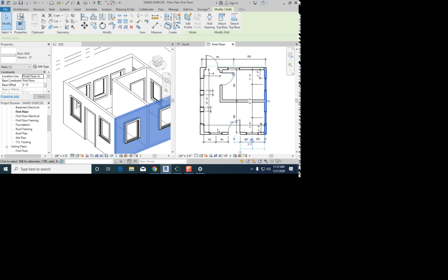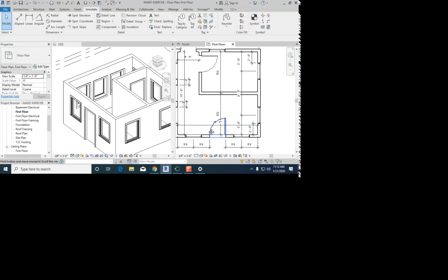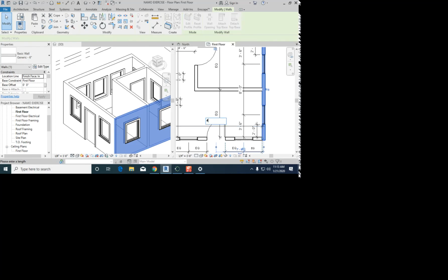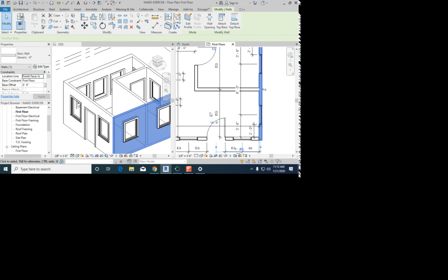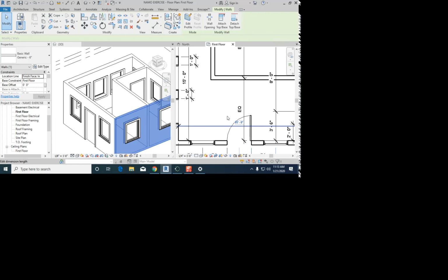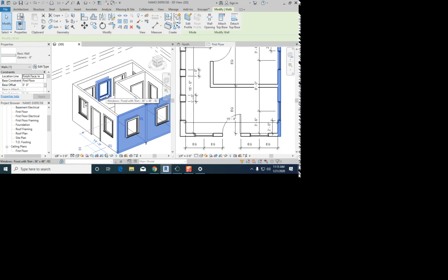And then Olivia, the other thing that you might have to do when you're done. So let's see. Alina, did you ask me earlier about changing the dimensions? So this will answer your question too. Let's say you put in your overall dimensions and you find out that you actually are at 14 and a half and not 15. Now you can grab your wall and change it to 15. And we love Revit because it moves the wall, it moves the window, it moves the door. It just knows everything just goes along with it, right? You can't move one and not the other.